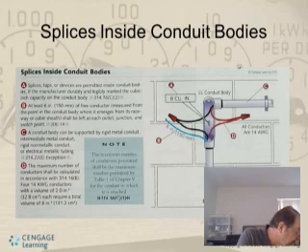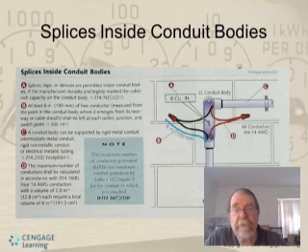There's a note here: the maximum number of conductors permitted shall be the maximum number permitted by Table 1 of Chapter 9 for the conductor to which it is attached. The maximum number of conductors shall be calculated in accordance with 314.16(A) and 314.16(B). For 4 14-gauge conductors, the volume of 2 cubic inches each requires a total volume of an 8 cubic inch box. It's just something to keep in mind when you see those.